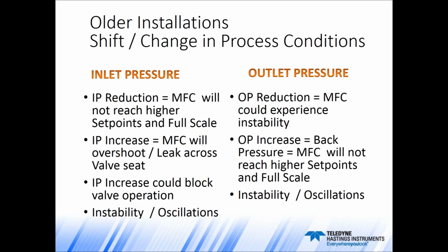An inlet pressure reduction will not allow the MFC to reach higher set points and full scale. So the backup pressure doesn't exist there to sustain the amount of flow that is contained in the full scale of the flow controller. An inlet pressure increase might produce a great overshoot for the flow controller and could also turn into a leak across the valve seat if the inlet pressure is majorly increased compared to the calibration pressure.